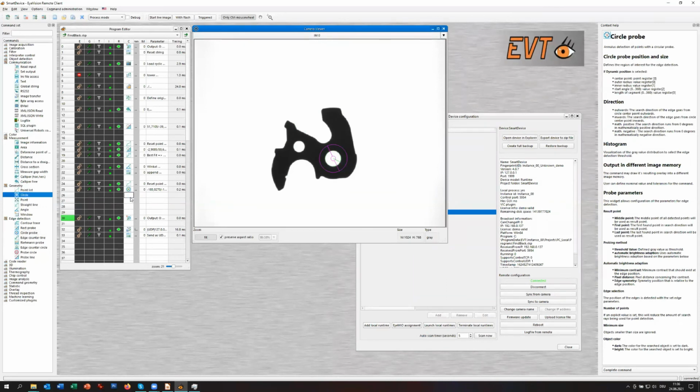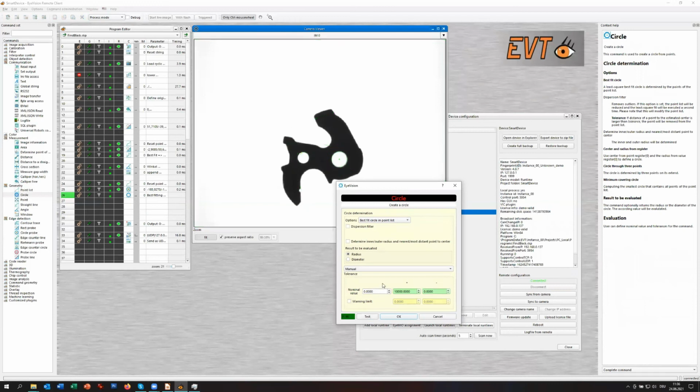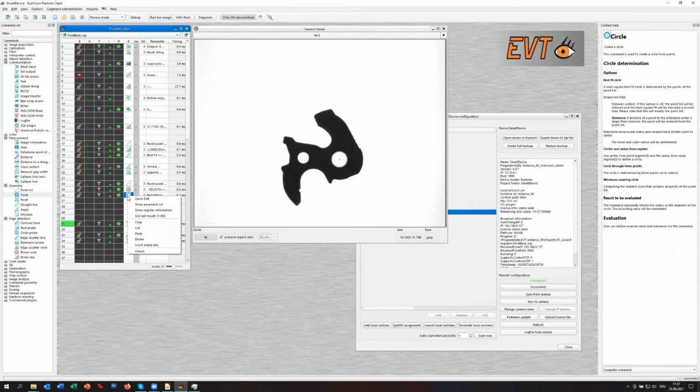And if you finished, as you have to do it with the straight line tool, you can use the best fit circle, which calculates the best fitting circle here inside. And as a result, we have this diameter. Based on this, we can do some additional resulting operations. So it's really easy to add and operate on tools, also to have everything under control.